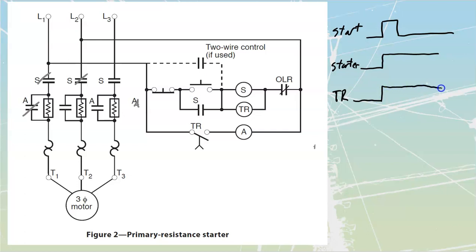And then the timing relay is going to start its timing. And after the timing relay has started its timing, it is then going to apply my accelerating relay. So we're just going to put this in over here as being T up to there. And then we see that that is going to be directly related to my accelerating relay, which is then going to go high at that point. Following this through, again from the top to the bottom over here, this is now going to be my motor at operation. We've got that timing that happens inside of there. And ultimately, when I hit my stop, oops, sorry, this is my A coil over here. Just put in my stop.